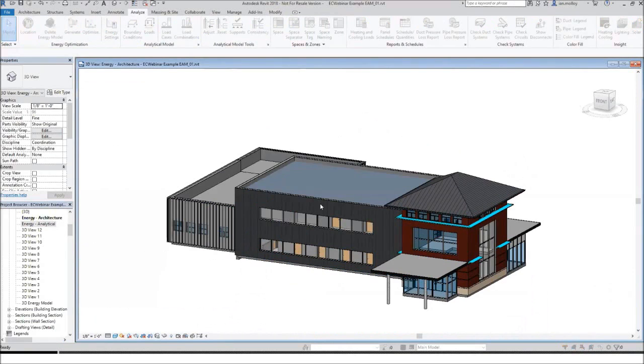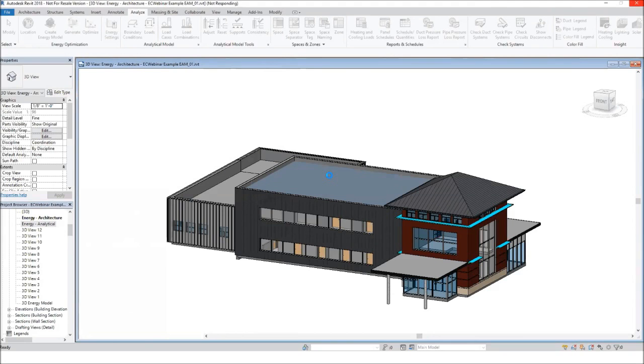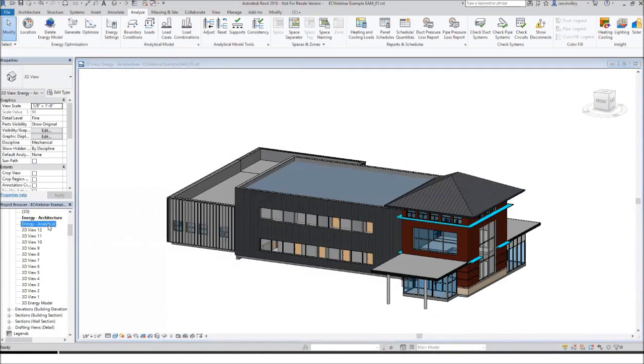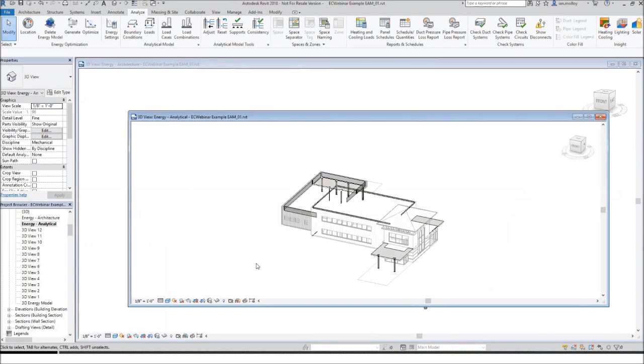So just one more time, let's delete that and create it again. This time, I think if I've remembered everything, it'll be complete. So that's essentially the steps. You start with a default resolution, look for shades. Sometimes it can look terrible to begin with, and you realize there are large parts missing from the model, or they're on a different phase or something like that. But once you resolve those differences and then get the resolution to the right level, you'll generally be able to get an energy model within a few percent of the physical measures, which is really quite remarkable, because energy model creation is normally one of simplification.